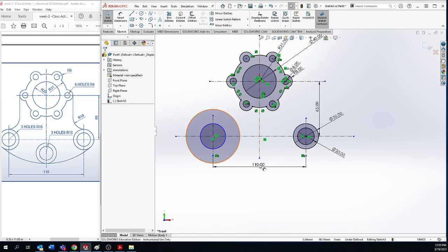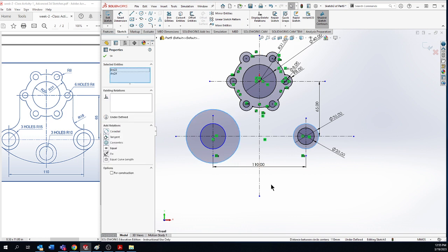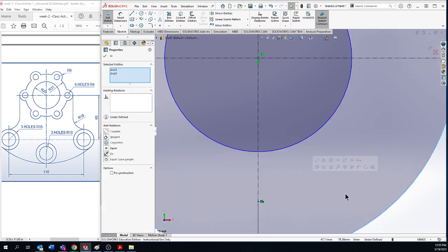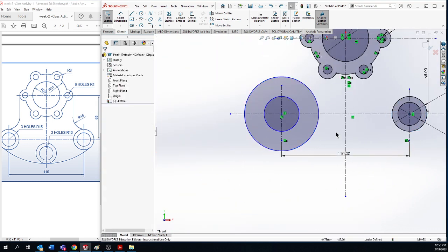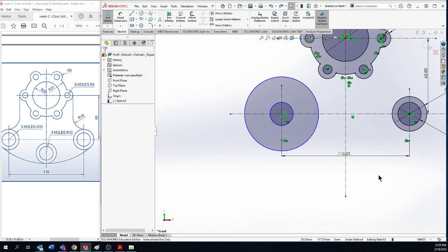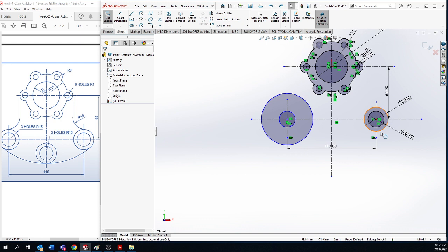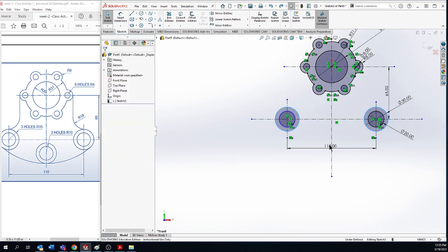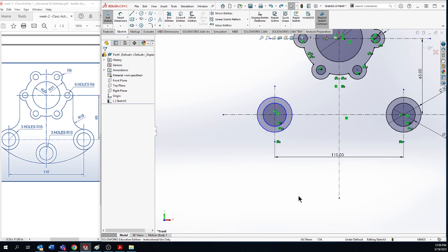Here also you can make one more circle, but before I just wanted to introduce equal relationship. Outer circle and press Ctrl and select this outer circle, make equal. Just zoom a bit, you will be able to see. So, it is very tough. Inner and inner equal, okay, and outer equal, okay,